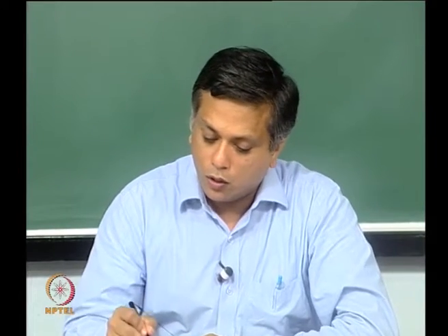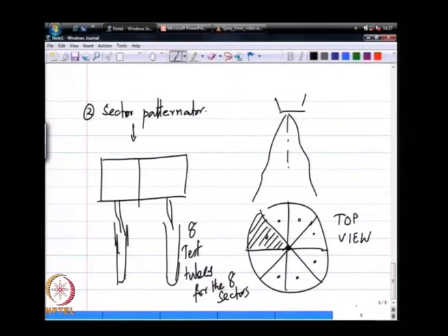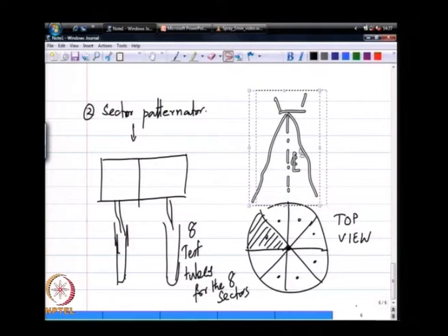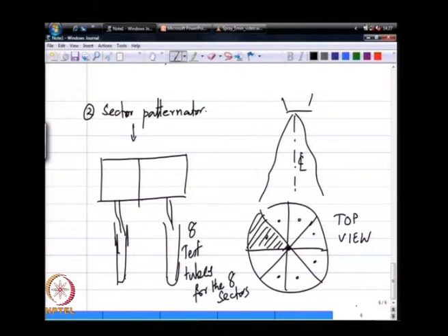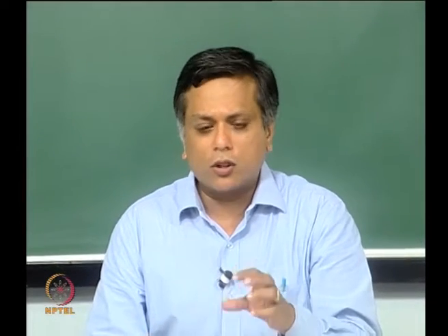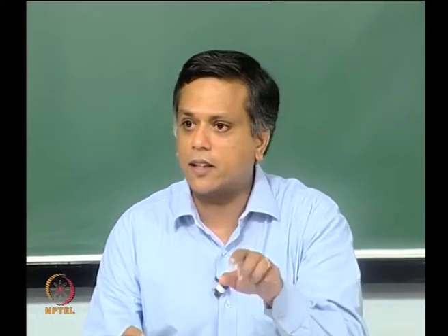Now, this is a perfect place to talk of the spray center line. Say if I take this sector patternator and displace it slightly. So, I am going to move the spray part out slightly, just about that far. So, this is my spray right now, where the center line of the patternator is also a geometric object. So, I can define an axis for it. Okay, it is only the spray that does not have a line that I can see, right.